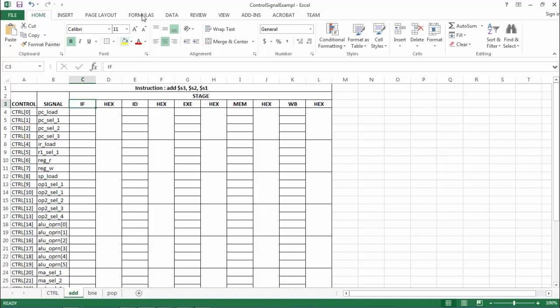We have the instruction fetch phase, instruction decode, instruction execute, memory. These are the state cycles, the five state cycles of the processor. This column is saying that if we list down all the bits and then group them into 4 bits from the LSB side, we end up with the hex equivalent of that bit pattern. But anyway, that will come later.